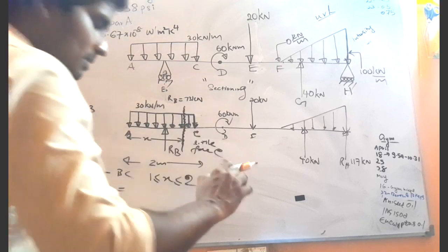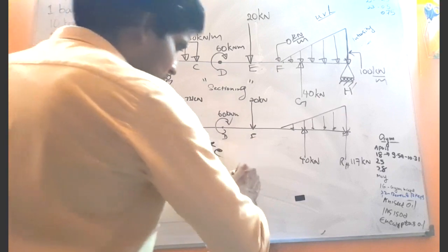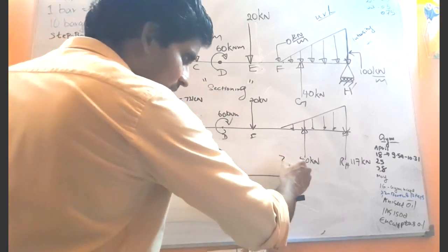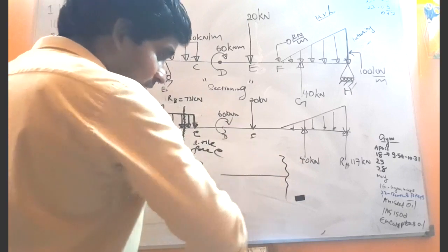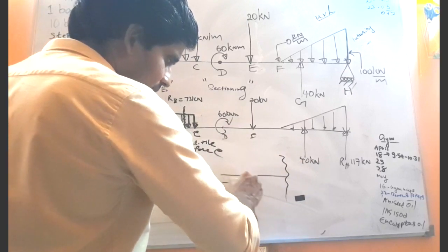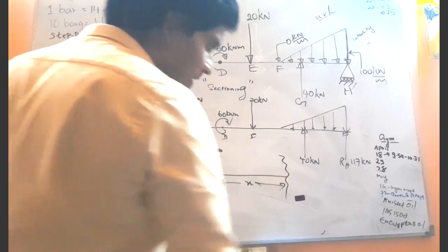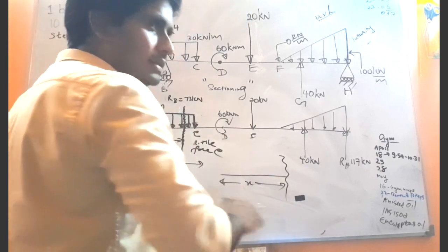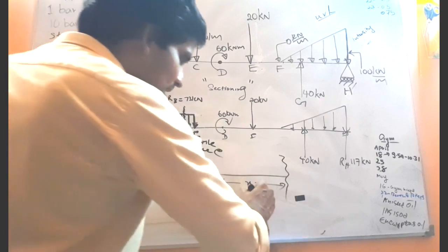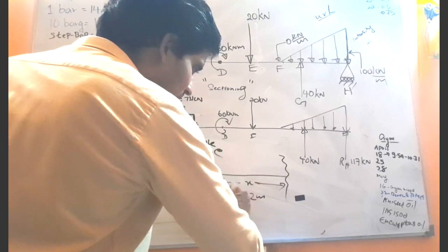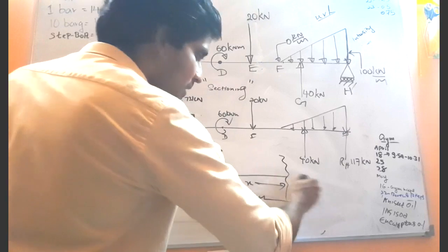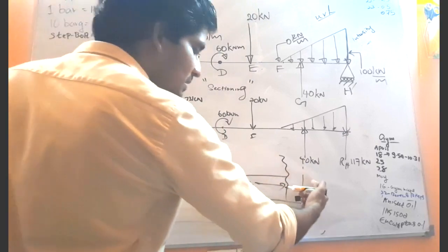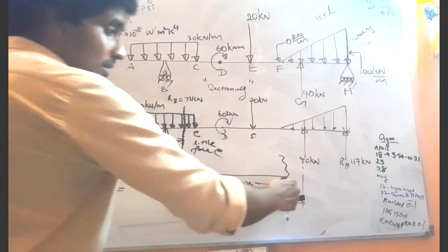Now when we are going to consider the bending moment, I will again write this section to have a better understanding, right? So now we have cut the section here, right? So what is the length of this section? That is x. Right? The length of this section is actually x, right? So now the entire section ends at a distance of 2 meters, right? Keep that in mind. Now 2 meters is somewhere here. So we are going to cut a little bit before the end.